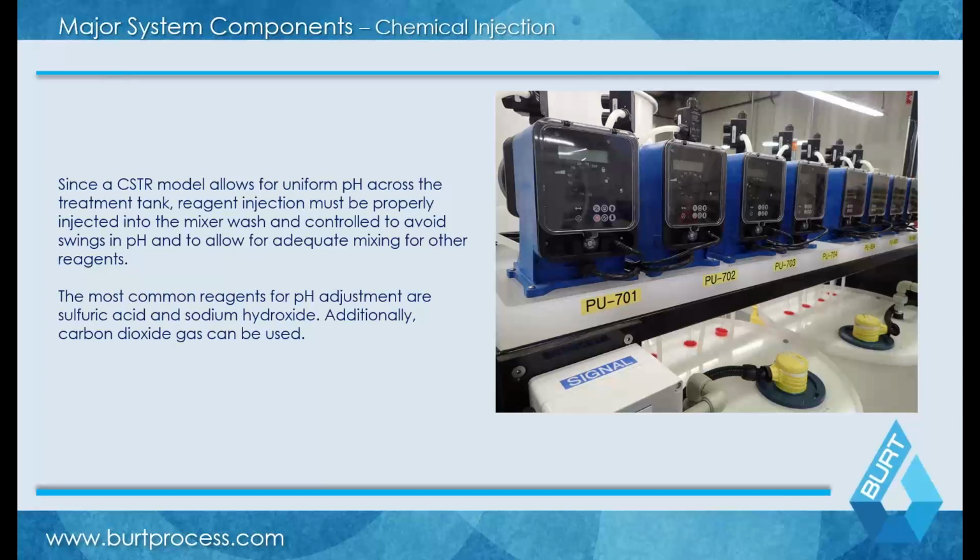A lot of that really comes back to owner preference. How do they want to handle the chemical? There is no fail-safe method. No matter which way you go, you do have to handle chemical one way or the other. Whether you're filling a reagent tank, you're going to have some kind of a drum or a built-in pump, which is going to pump out of your tote or chemical drum into these tanks. If you're replacing drums, now you're bringing up a drum, you're pulling the suction wand, you can see here, out of your system and then placing them in place.